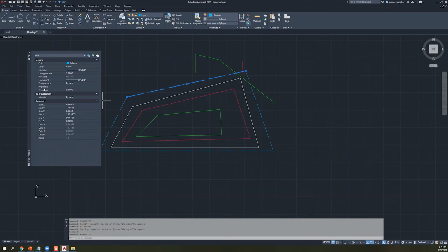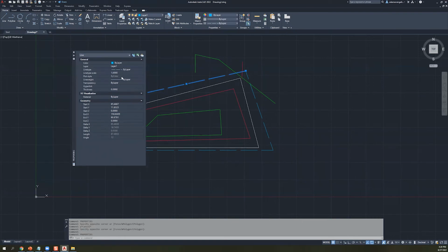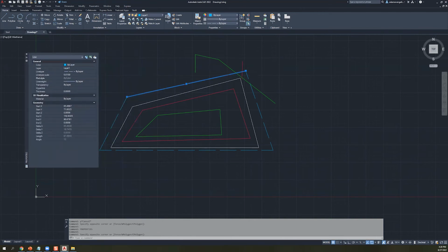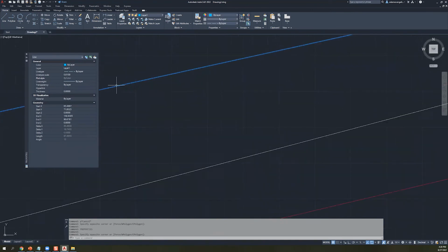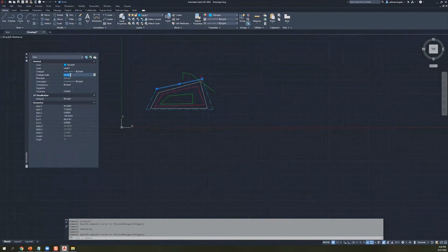So looking at this object over here, what do we got? There's a few other things you might be interested in. I think in particular, the line type scale is a common feature that shows up. We're obviously in ISO kind of scaling right now, but oftentimes depending on the size of your drawing and the size of your actual styles, this might need to be adjusted. So like 0.01, for example, would look something like this, where not necessarily what we wanted, but it's just really small. It'll depend on scale and everything like that.